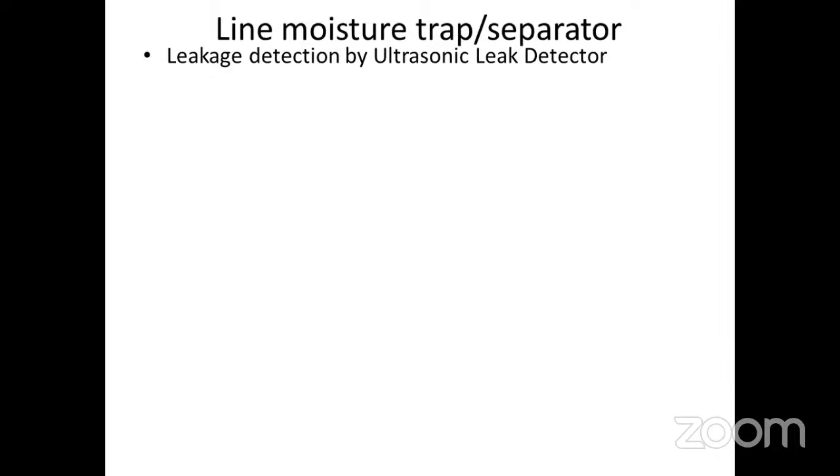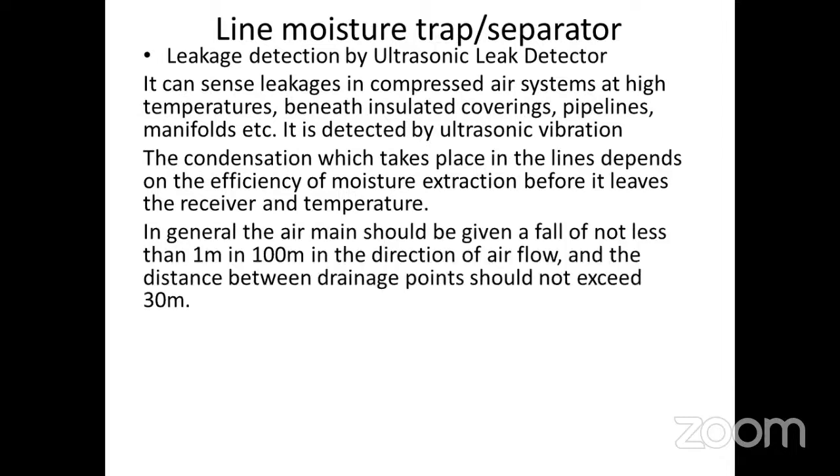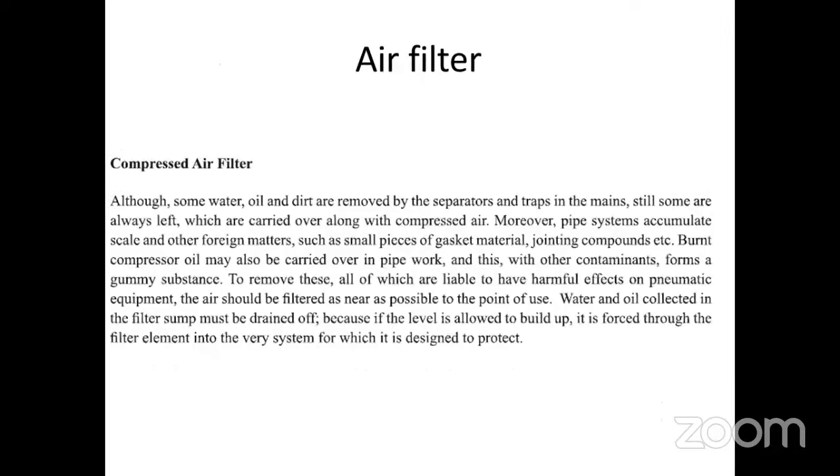Moisture trap, ultrasonic detector. The condensation should take place and the moisture extraction before it leaves the receiver. Drainage points are provided at equal intervals. They are manually draining it. Sometimes we used to have timer based draining also. That has to be optimized also, because compressed air will also be lost during draining, sir.